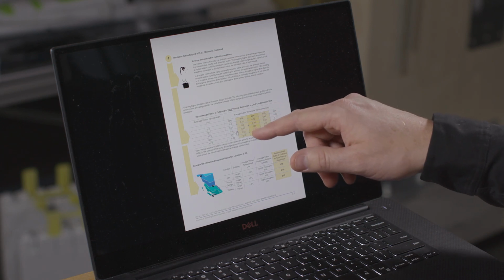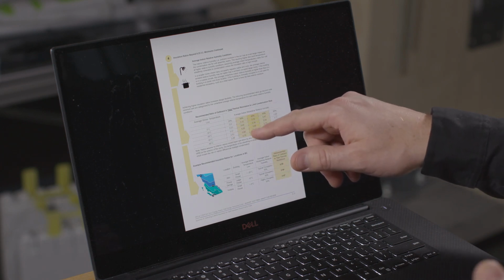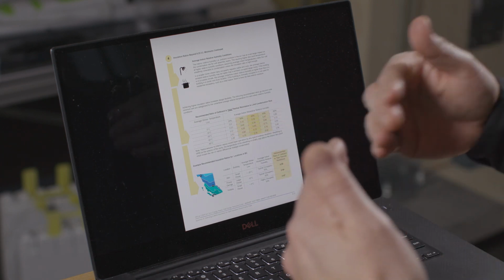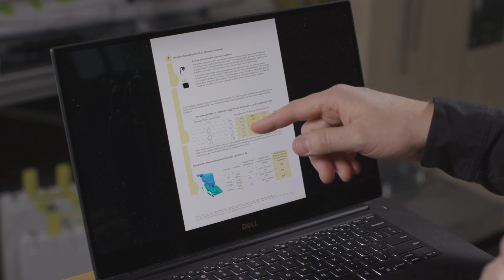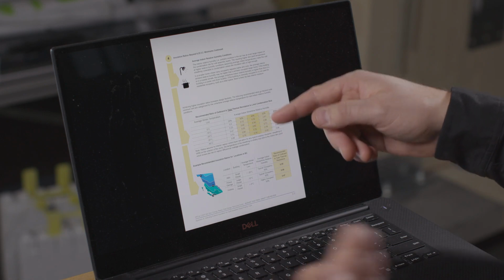And so you can see here, the colder it gets, generally the more exterior insulation you need. With exterior insulation, you may find that you need up to 2/3 or 70 or 80% of the insulation on the outside before you look at the vapor control on the inside. So depending on what this table tells you, that's the ideal ratio. If you don't have it, that's not a problem. If you do have it, it sets a different criteria.